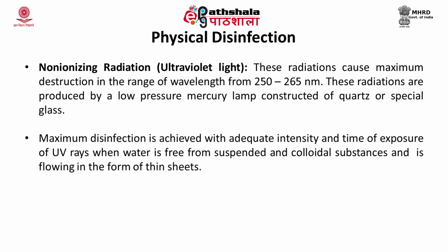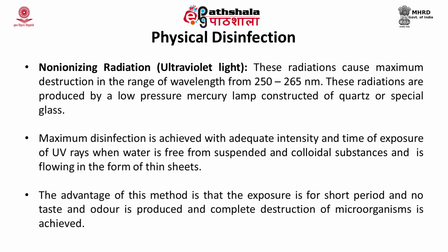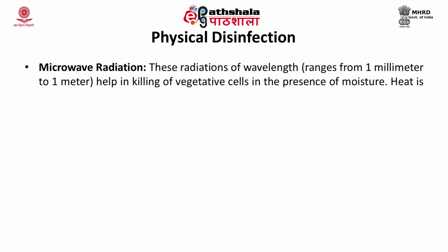Maximum disinfection is achieved with adequate intensity and time of exposure of UV rays with water which is free from suspended and colloidal substances, flowing in the form of thin sheets. The advantage of this method is that the exposure is for a short period of time, no taste and odor is produced, and complete destruction of microorganisms is achieved.